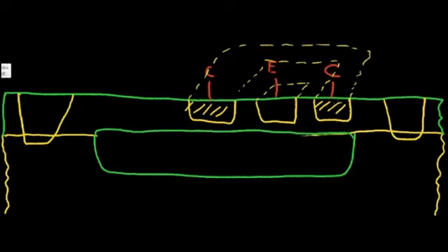Now I want to put in another diffusion layer, which is an N-type material. It's the same layer used for the emitter of the NPN transistor. It's a highly doped N material. This is a highly doped N material in the buried layer. This is a lightly doped N material, I'll call it N minus.